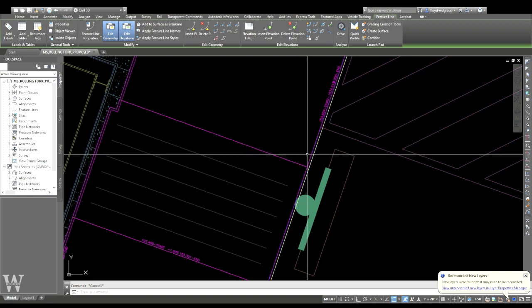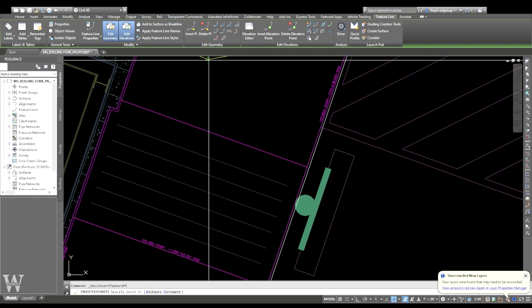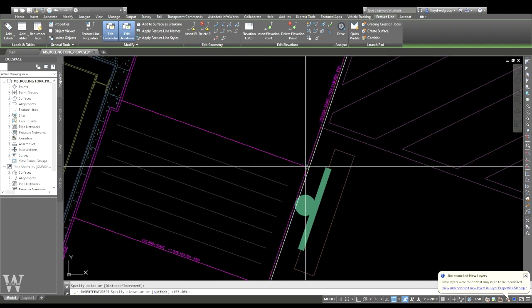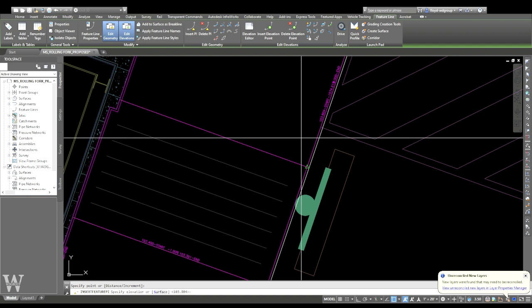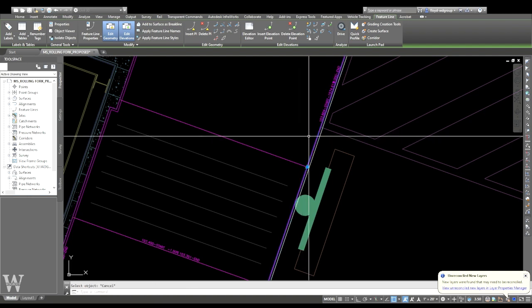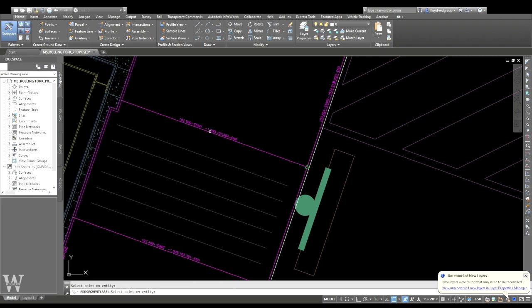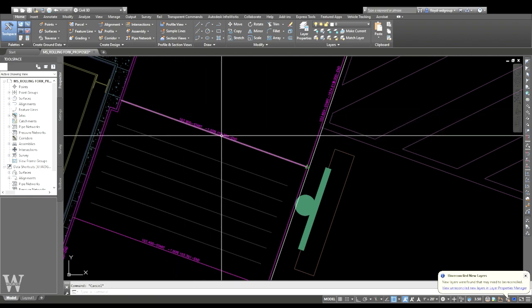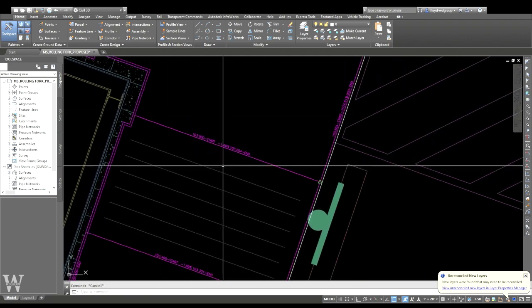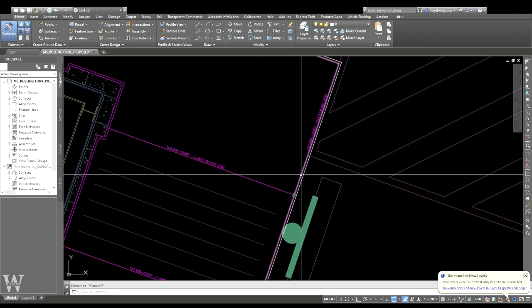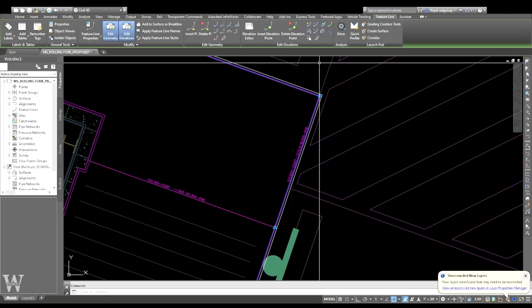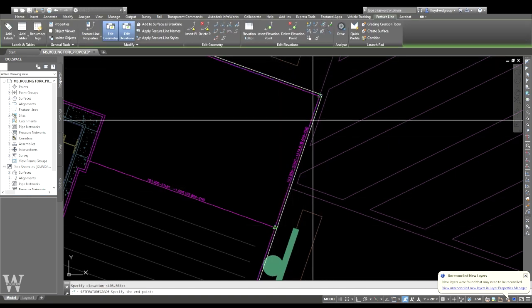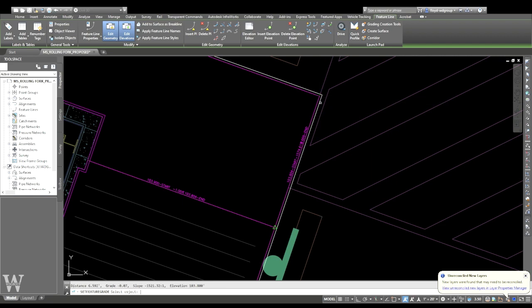So let's fix that. So what we're going to do is we're going to come in here, we're going to insert PIs, we're going to click it right there. I don't know if that elevation is right or not. Why don't I know? Because I didn't label that line right there. So now I'm going to have to go here and just default with it because I don't know what it's supposed to be. Add that one, 103.9. So it was supposed to be 103.84, but that's why I use the add label, because of things like that. If I'd have had that labeled, I wouldn't have had to guess. I would have known for sure. Now I can come in here, that point, I'm going to make that 103.8.